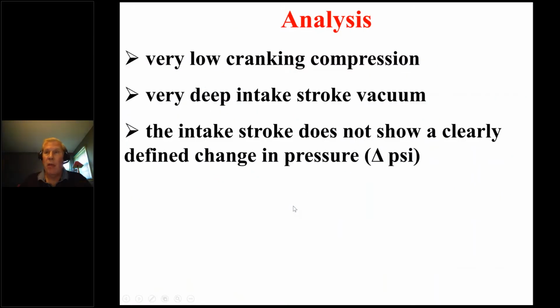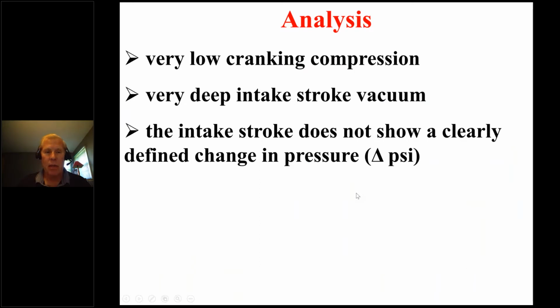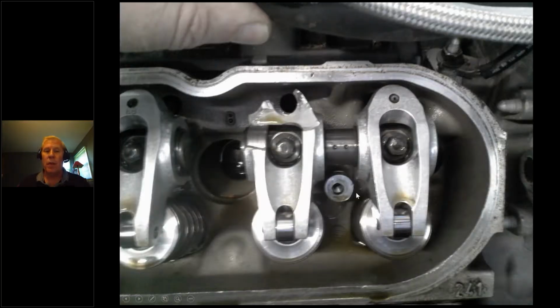So if I look at some analysis, I got super low compression. I got a very deep intake stroke, vacuum or pull, and I don't really see a clearly defined change here. And I know you know what's wrong. The intake valve's not opening.